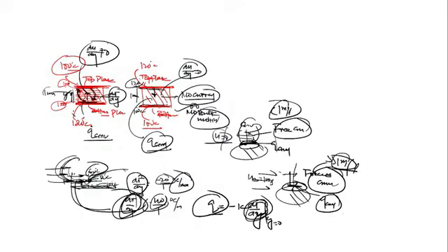That heat transferred through the wall is then transported into the remaining fluid via convection, because at the wall the fluid is stationary, but away from the wall the fluid is in motion. So whatever heat is transferred via conduction is propagated into the rest of the fluid via convection. Yes or no, Deepika?